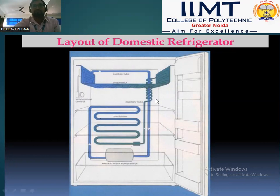Saturated liquid refrigerant is supplied to the expansion device. The expansion device reduces the temperature as well as pressure. Low temperature, low pressure liquid refrigerant is supplied to the evaporator, absorbs the heat inside the cabin, and vaporizes. This cycle is repeated again in the vapor compression system. The example of a domestic refrigerator.